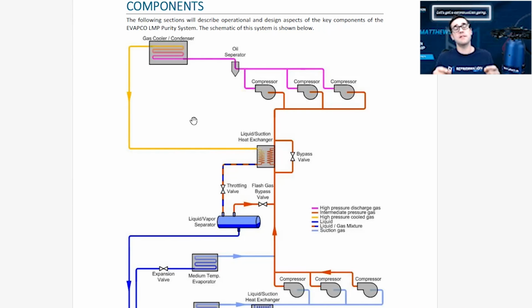This is key to know, because whoever's doing the startup will stop that. If the manufacturer's there, or the inspection agent or the local jurisdiction, and I don't know how often that comes in, they're checking the pipe to make sure. And on the legend of this piping schematic, this P&ID, it should have what section of pipes they're using, because as the size of the pipe goes up, the pressure rating goes down. You're like, well, what do you mean?